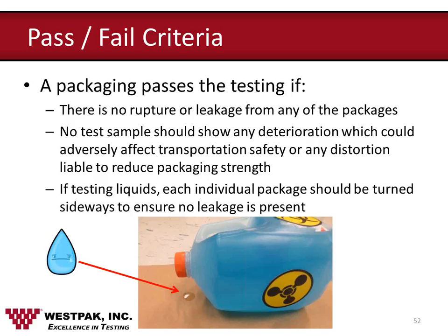But let me give you another example. For instance, if you do a vibration test, and after the 1 hour vibration, in addition to the scuffing, the result was that your tape was scuffed off and the 2 flaps were barely hanging onto each other. That would be a failure because that is obviously a liability and has deteriorated the package in a way that affects its shippability. You can't ship that package anymore.